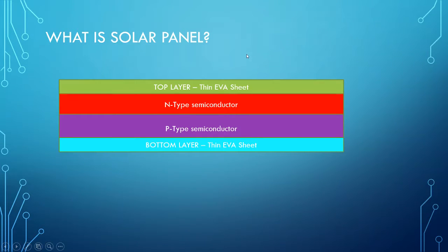So sunlight is continuously coming and it has photon energy. That photon energy is continuously creating electron plus hole pairs in the depletion region, and electrons are going to p-type semiconductor, and holes, I mean positive charge ions, are going to n-type semiconductor. So over a period of time, this plate is totally charged with positive ions, and this one is totally charged with negative ions.